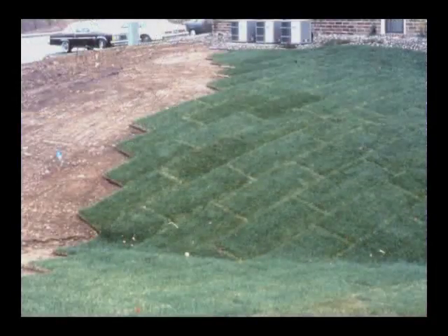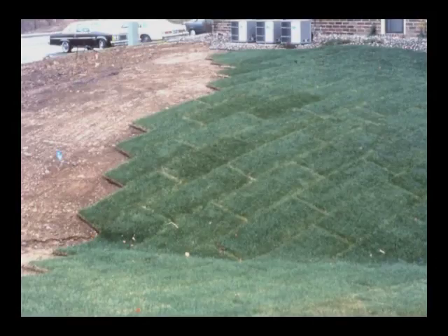On areas that require immediate vegetation or a high-quality turf, sod may be considered as an alternative to seeding. Sod is expensive and prone to failure if irrigation is not available. The sod must be installed with the joints staggered, seams closely abutted but not overlapping, and staked in areas of concentrated flow or with steep slopes.